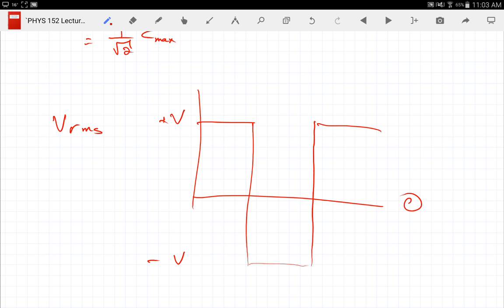So are there circumstances when one side will have more of a spike than the other side, and it's not even? Okay. Are there situations where it's not centered on 0? That's what you're saying, where you have an offset. You can make a situation with an offset, but a generator won't have an offset. The generator will be balanced around whatever you put for your ground. Now, if you change the ground to something else, well, that's how you put the offset in.